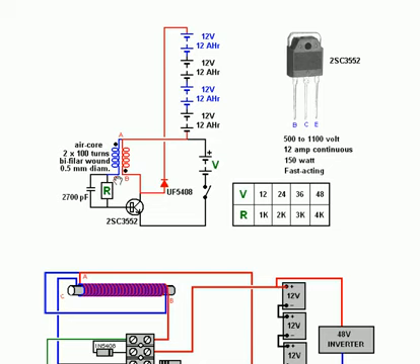Now the thing about a coil switching off is that it pulls the collector of this transistor up to a very high voltage until it exceeds the voltage of the battery bank that you're applying it to.